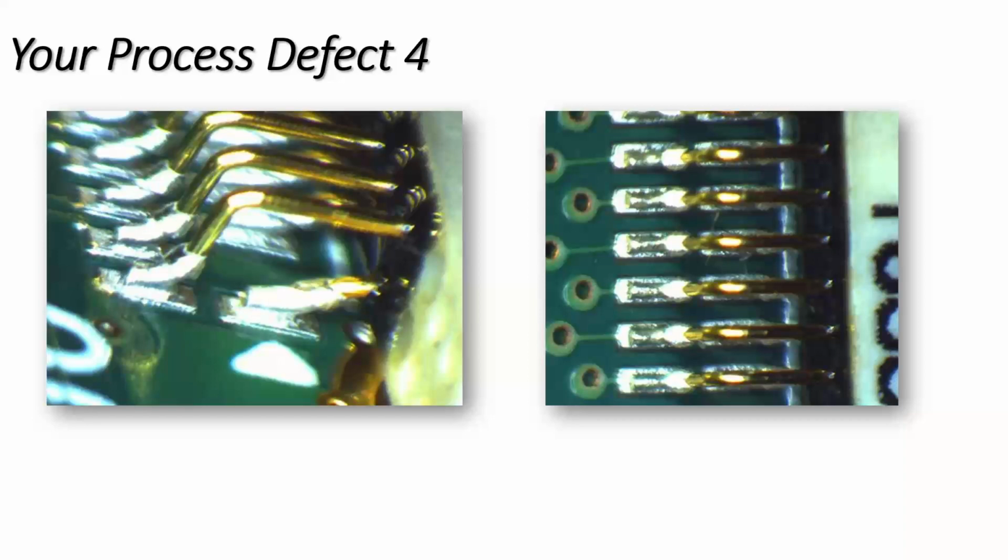So what I tend to do in a situation where I've got a high mass component sometimes, or I've got an intrusive reflow design, or in this situation where I'm getting wicking, I tend to put more heat in from the bottom. Now, remember that a convection oven is basically a lot of blowers, but remember where the convection comes from. It comes from a solid slab, or from a panel which is emitting hot air to the system. But that panel, that heater, can radiate heat. I know nobody wants to talk about radiation, but it's a mass.